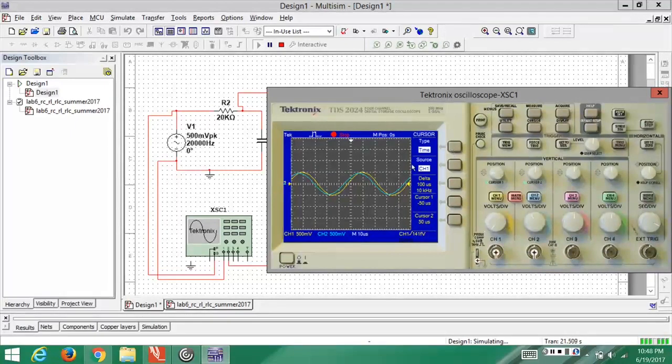I was going for the yellow waveform, which is channel 1, so my source will be channel 1. The cursor for channel 1 is now on the screen. You can see them at the leftmost and rightmost positions of the screen. I need to bring them to a convenient place where I think the cycle started, and the second cursor to a place where I think the cycle ended. To move the cursors, use channel 1's vertical positioning knob and keep it moving. As you can see, the cursor perpendicular to the time axis is moving.